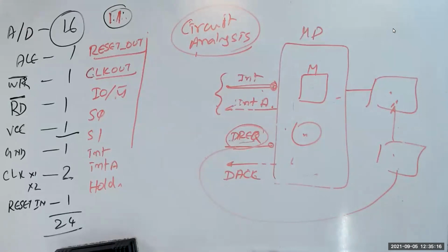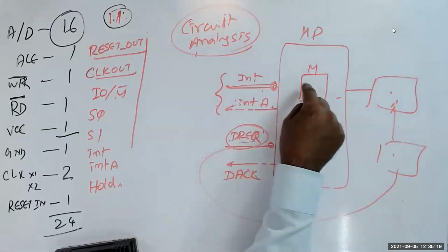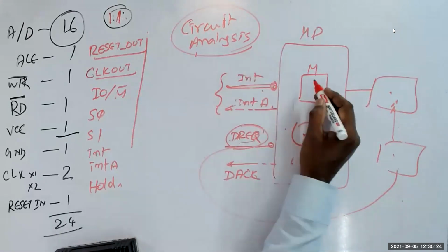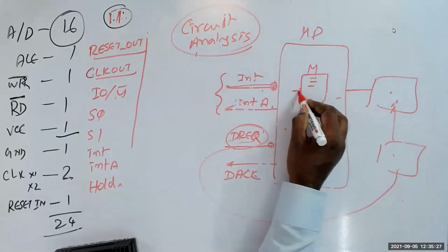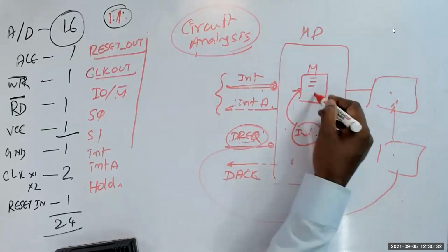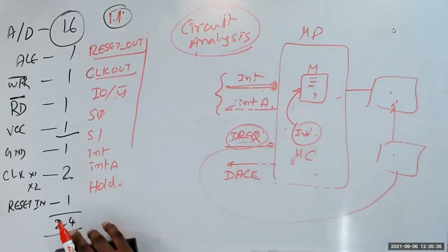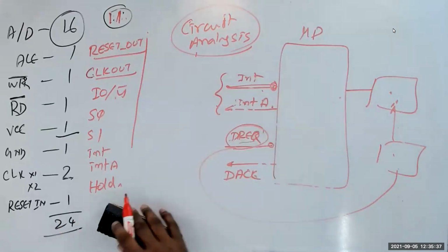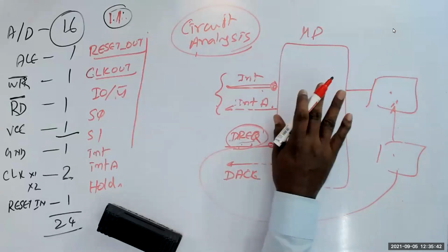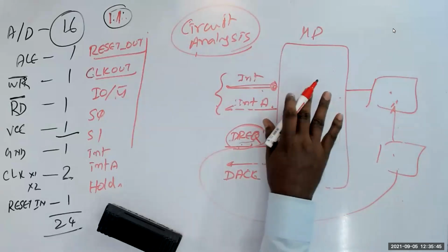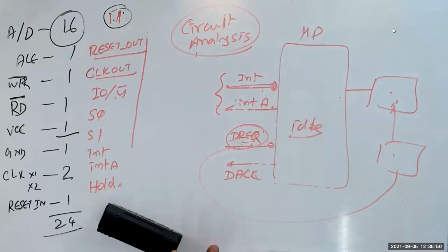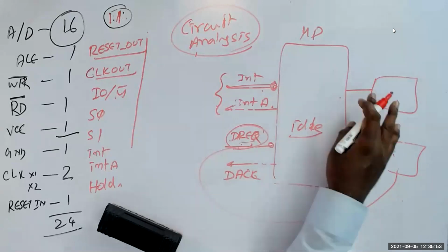So there's a difference here. When I give an interrupt, I'm telling the microprocessor to stop the main program wherever it is, and go to the other important activity. I will do that, but both are done by the microprocessor. It is not going idle. Whereas when I give a DMA request, the microprocessor goes to idle mode. That means he is not going to do anything. He is going to keep quiet and give the memory to somebody else. He will switch off. I'm taking a rest.